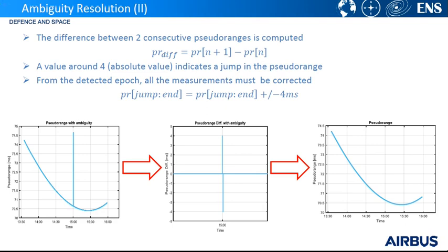Before we start processing the collected data, it is important to remember about the possibility to cut the files, for example, by selecting a particular constellation. In that way, we will have smaller files and the processing will be faster.